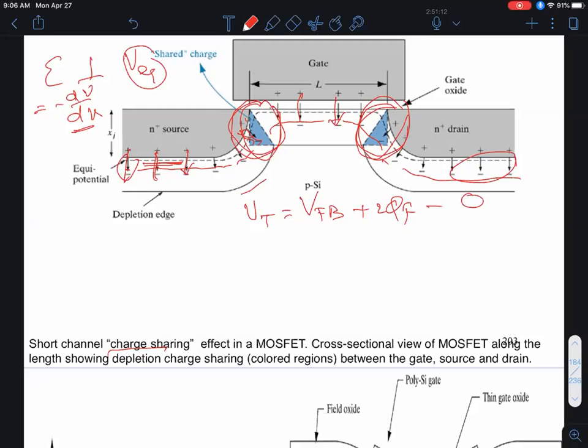And then finally, you had the depletion charge over Ci, the insulator capacitance, where the depletion charge for an N-channel device, where I have acceptors in the channel region, is minus q Na times W, okay? This minus and this minus make the final term positive.